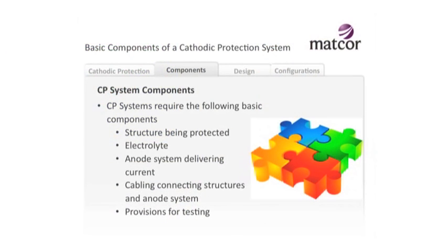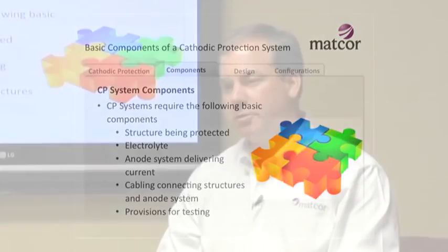We don't do well with atmospheric applications because the air does not allow the conduction of electricity. But we're great if you've got something in water, seawater, or soil. Most of our applications are in those 3 electrolytes, or 2 electrolytes. The other one is concrete. We actually can protect metal in concrete like reinforcing steel.